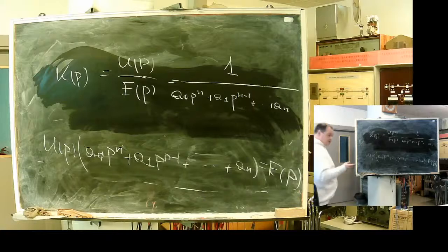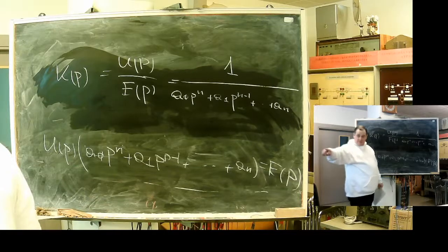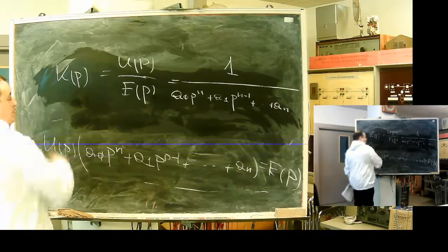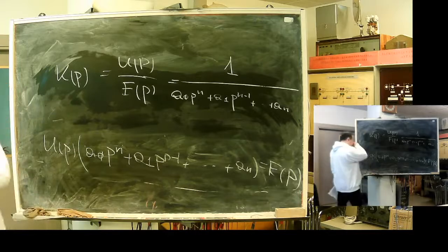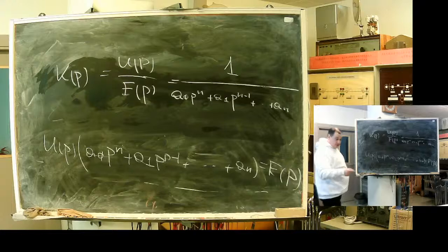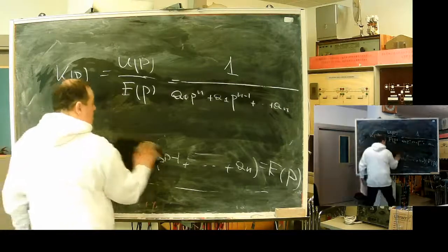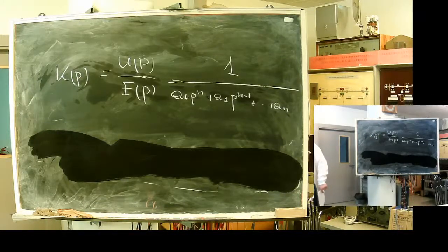Zeros of the characteristic equation mean the own frequencies of the system, frequencies at which the system will oscillate or go exponentially down. Each such frequency equals the point where the transfer function becomes infinite, because you have division by zero here. Each pole, or point frequency at which the transfer function goes infinite, means an own frequency and a potential point of instability. Then the characteristic equation will be zero. It may go down, oscillate with decaying oscillation, or it may go up.